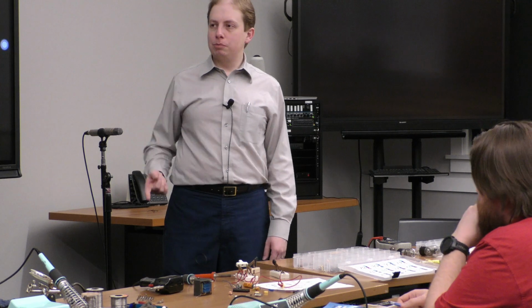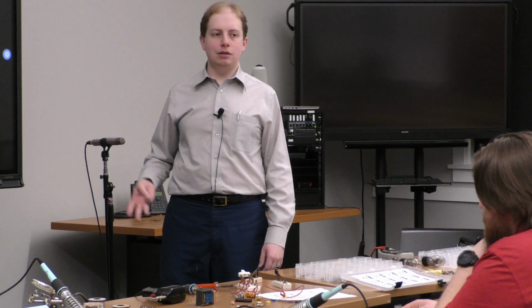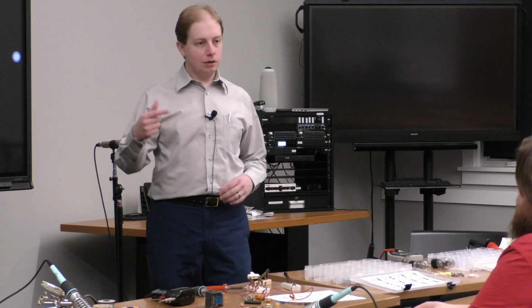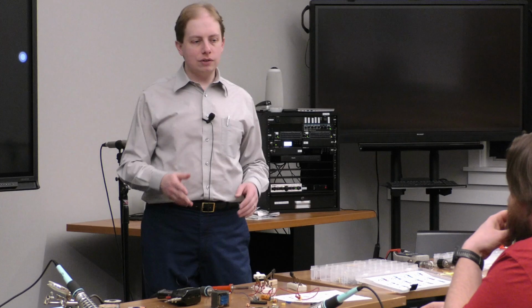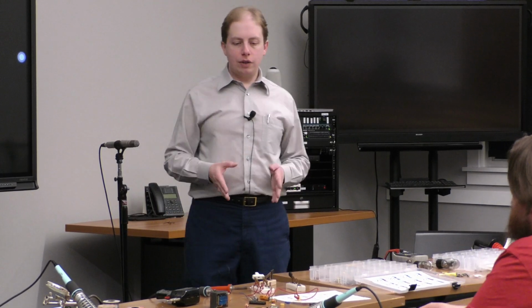So if you wanted the East Jordan repeater and the Petoskey repeater and the Mancelona repeater, you had to get crystal sets, transmit and receive, for each of those frequency pairs. But even nowadays with synthesized radios that you don't need crystals in that sense, you see crystals all the time in tuned circuits because they offer a very stable frequency source to get the exact frequency.